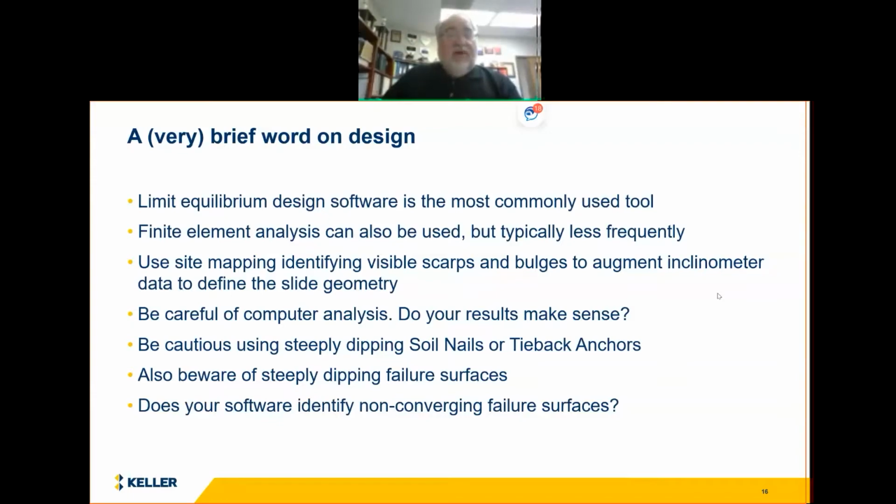Finite element analysis can also be used, but it's typically used much less frequently in slope stability. It's still used by some folks, particularly in real high profile projects, et cetera. But there are so many input parameters involved that it's much more sensitive to the soil parameters and the answers you get. So typically people use limit equilibrium.